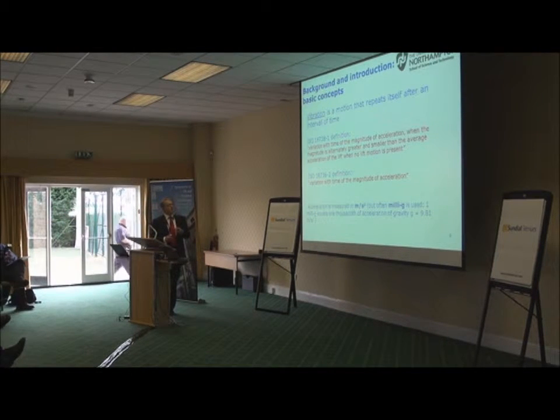This standard tells us that variation with time of the magnitude of acceleration, when the magnitude is alternately greater and smaller than the average acceleration of the lift, when no lift motion is present, is vibration. ISO 18738-2 gives a similar but shorter definition.